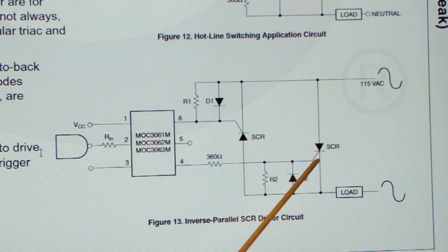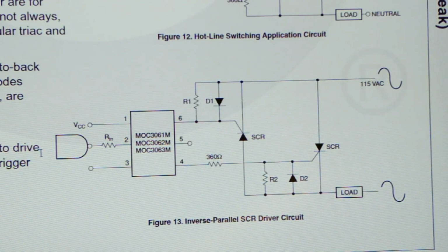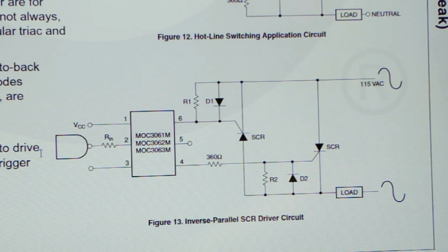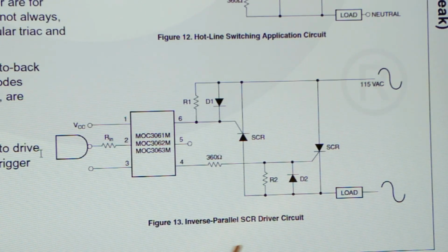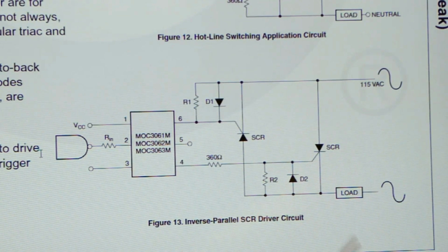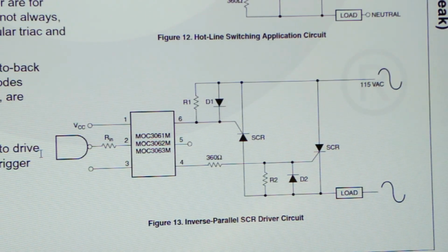So I'm getting like a 10 volt RMS voltage drop, which is causing, if you hook up the Variac transformer to an isolation transformer, the isolation transformer starts making a loud humming noise, because you got an oscillation. The voltage drop is actually an oscillation, 10 volt RMS. But I'll show you that on the oscilloscope.